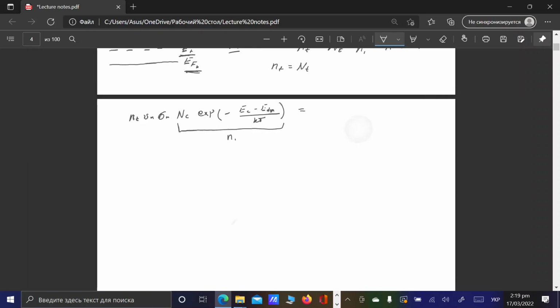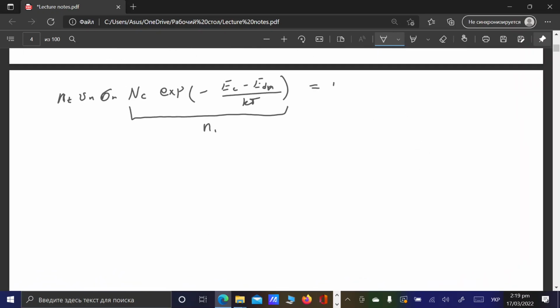So that obviously will be proportional to the total concentration of holes in the valence band, thermal speed of holes, capture cross section of a hole, and number of available electrons on these energy levels in order to recombine. So we need to put here NT.